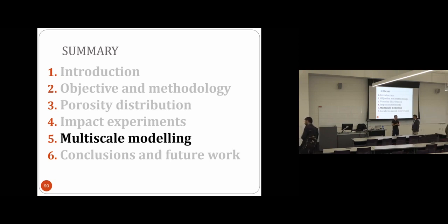What I was going to say is that the mechanical properties of additive manufacturing and the mechanical properties of traditional manufacturing are never the same. In fact, I was testing printed titanium and titanium produced in the usual manner, and the yield strength of the printed titanium was higher. So this complicates everything in order to say what is better.